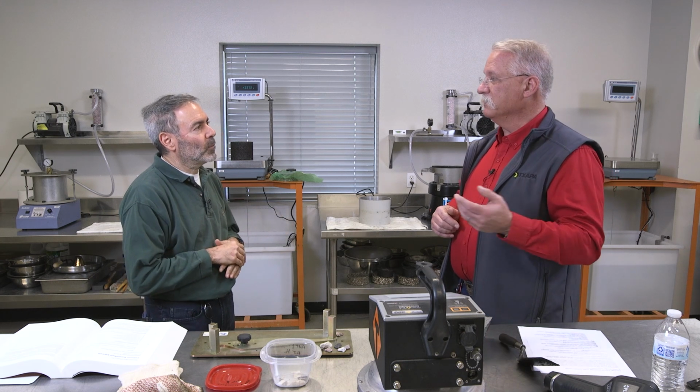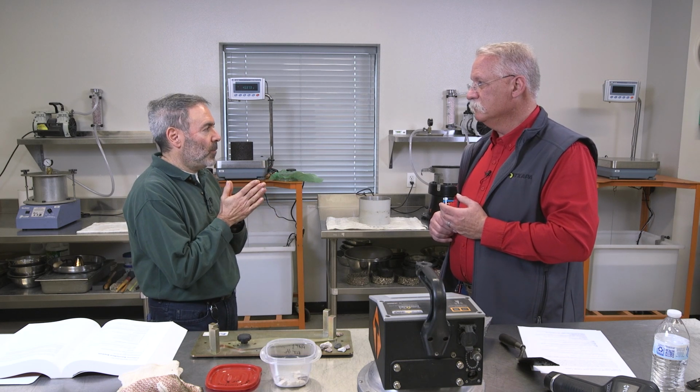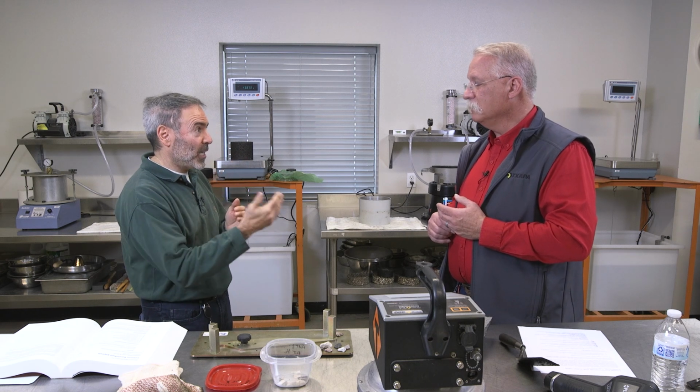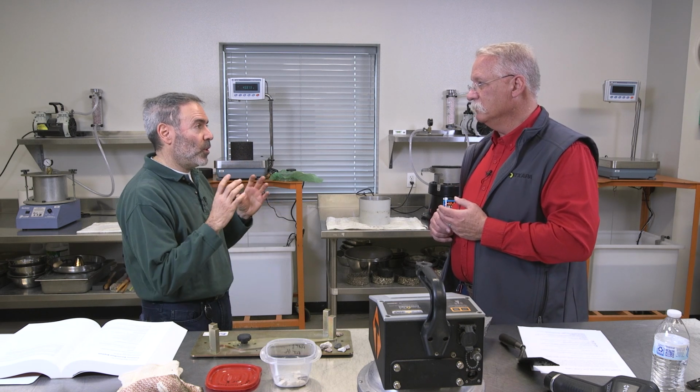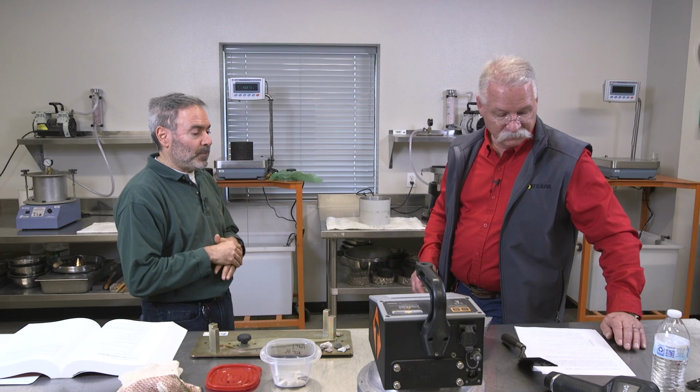Then why does the contractor test? Well, it's like a control chart. They need to know that they're maintaining. They got to test the ingredients like asphalt content and gradation, to ensure the final product meets that specification.